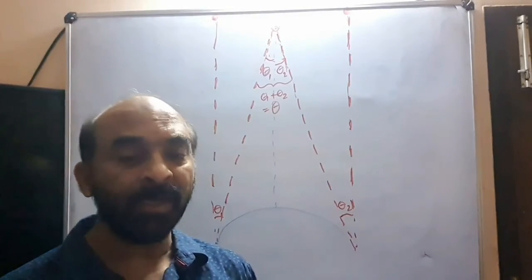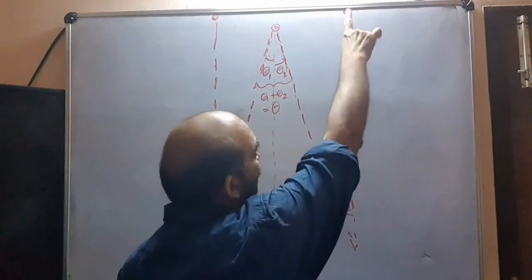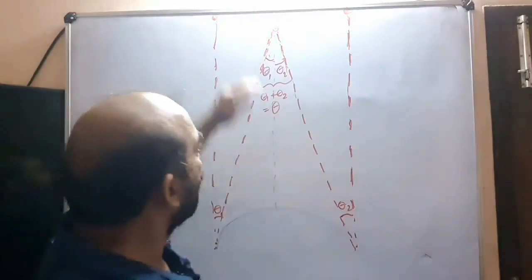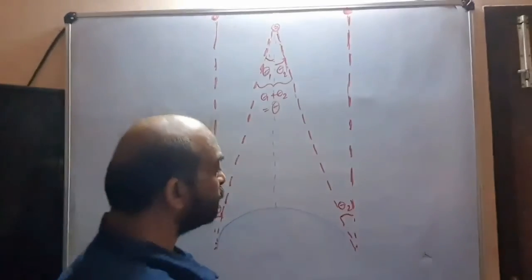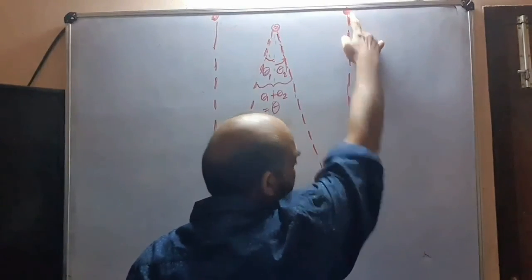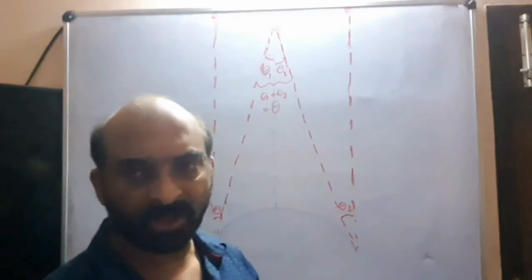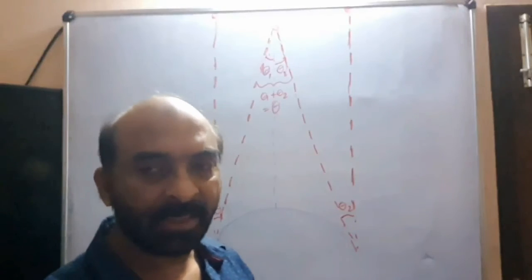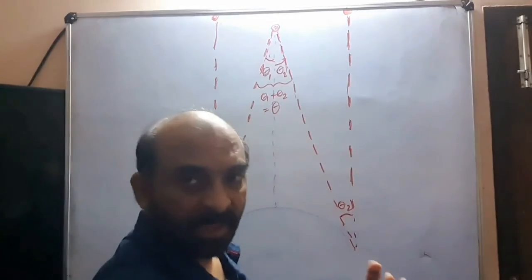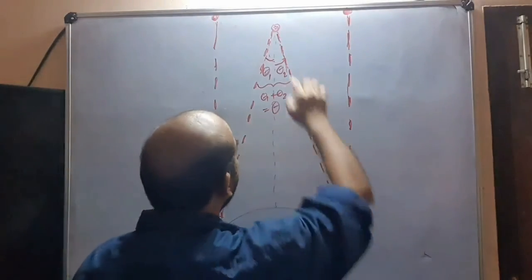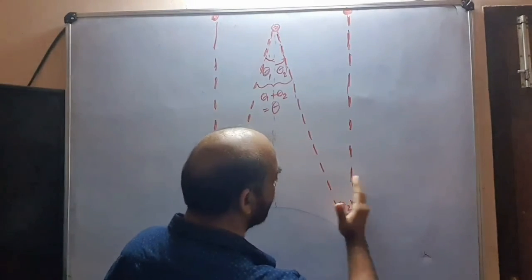In order to get that angle, while you start experimentation, you have to find another star which is far beyond this star. First you observe that star just above, observing through the telescope, and make its reading 0 when you see this star. Now you start turning the telescope until you see the star under concern. Then there will be an angle registered there.